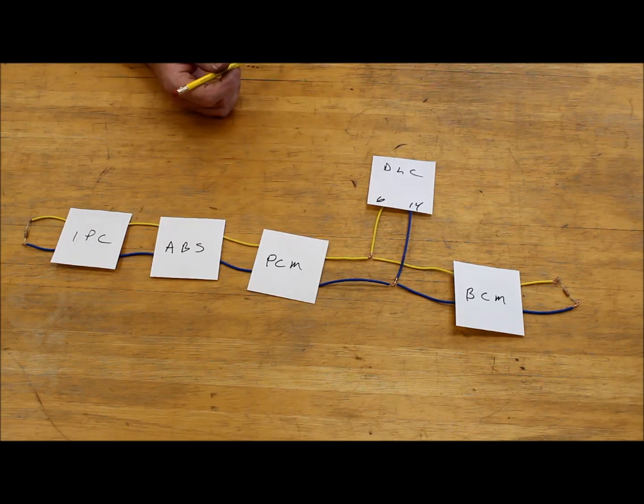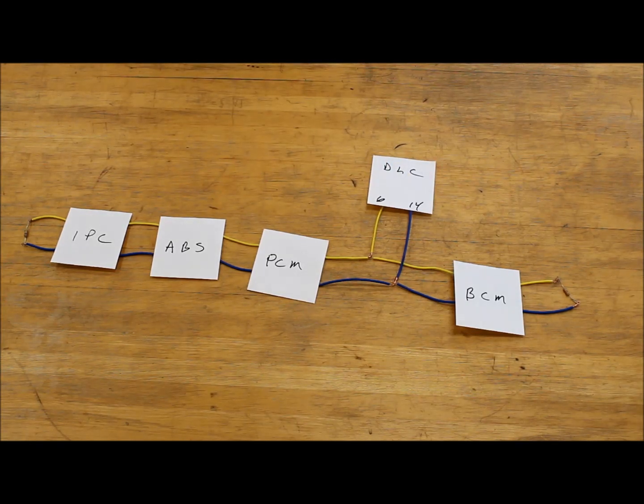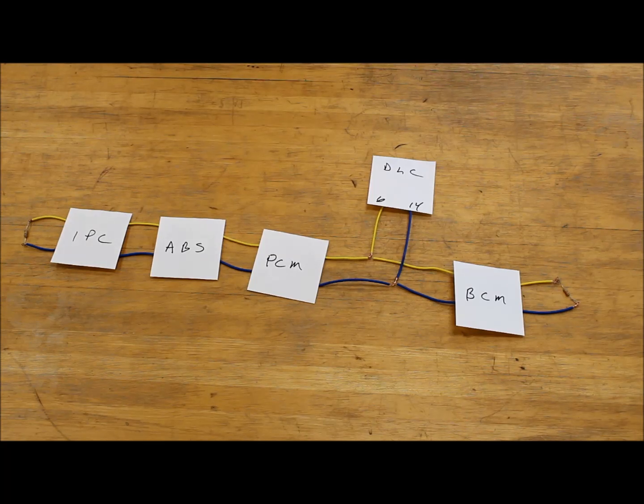So we'll look at the wiring diagram for, I think it's a 2010 Chevy, where we see the high-speed CAN network. You'll see that it comes to the data link connector at pins 6 and 14. So if we plug a scan tool into this car, through these 2 pins, that scan tool is able to access all of these modules that are on that network.